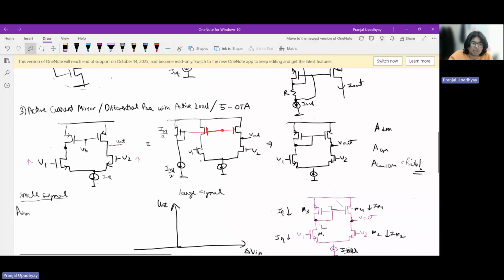So this is the basic idea: for a differential circuit we can have an active load. It's not technically correct to call it an active load, but anyway, basically what we are doing is using transistors as our load for the differential pair. And so this is the basic configuration. We need to decide certain V bias so that they can act as a load of suitable value.